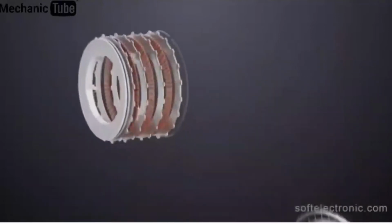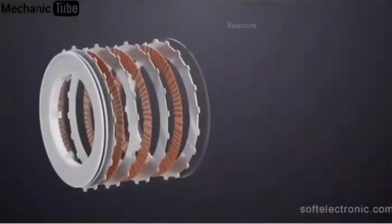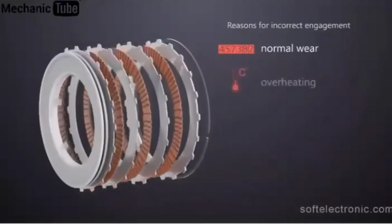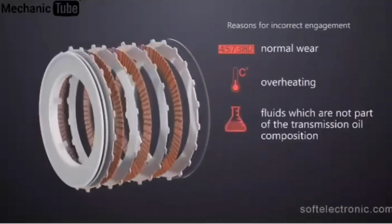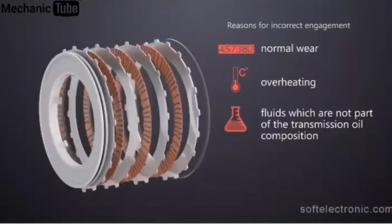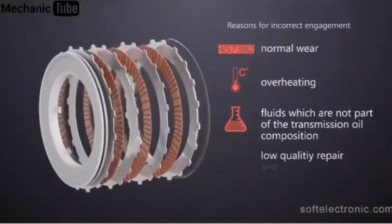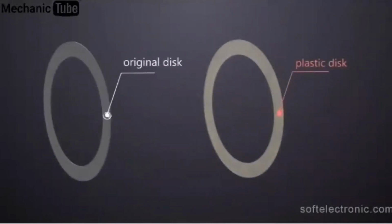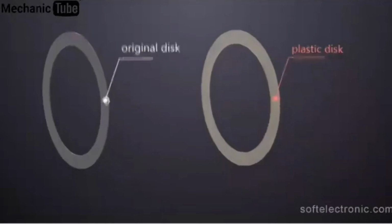The malfunctioning of the lockup mechanisms may be due to normal wear, overheating, the entering of fluids which are not part of the transmission oil composition, or previous repair with low-quality parts. Soft Electronics technicians have seen torque converters where the clutch discs have been replaced with plastic ones after a previous repair.